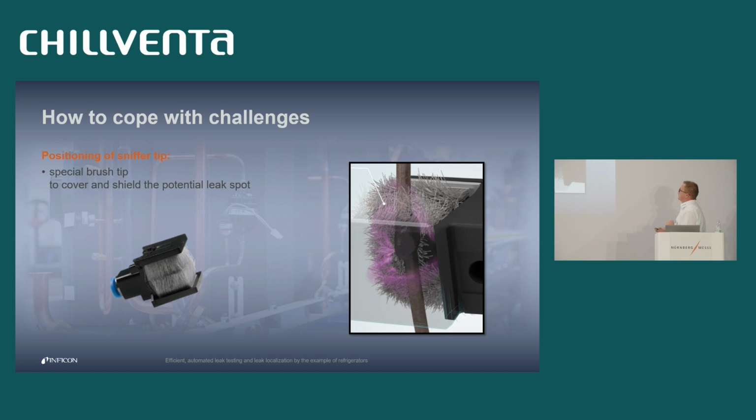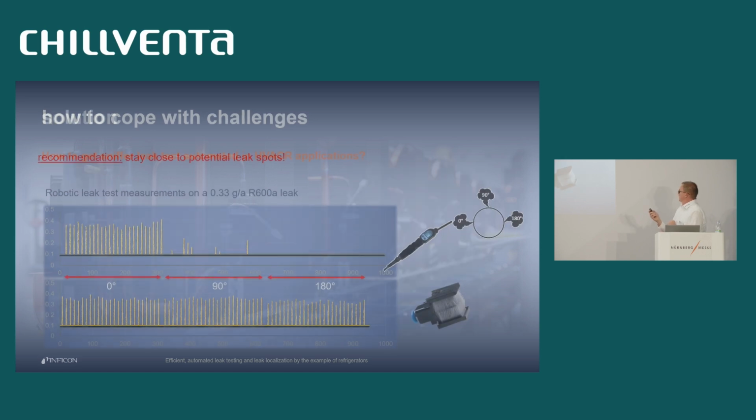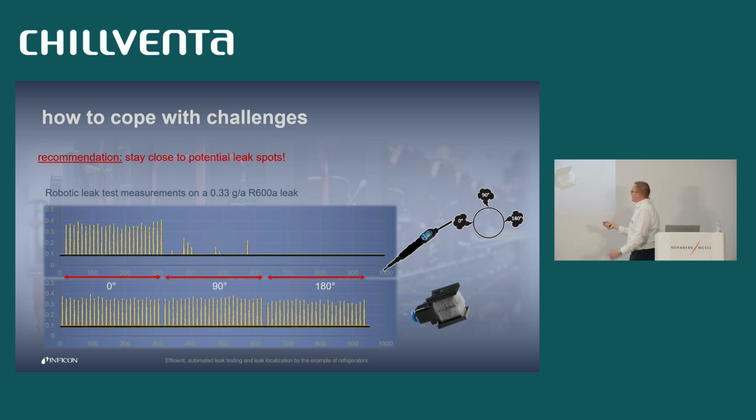And with that solution, we found out, hey, it doesn't really matter where the position of the leak is. If it's 0 degree, 90 or 180 degree, the measurements are almost the same, and in each case, you will catch the leak.